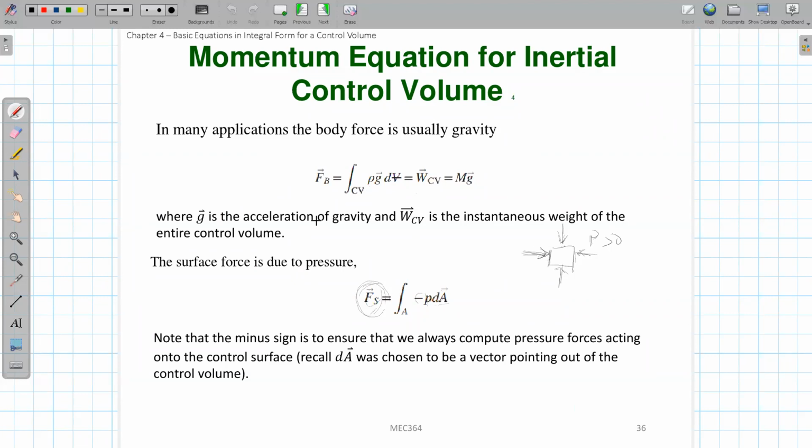So momentum is changing. It also means that velocity is changing, right? And another thing I want to mention to you before I do that is these basic laws. Right now we have introduced these two basic laws, the conservation of the mass and the conservation of the momentum. They work for fluid dynamics at the same time. It does not mean that when I'm using the mass conservation, I cannot use the conservation of the momentum. No, you can always apply both the mass conservation and Newton's second law at the same time to a problem.